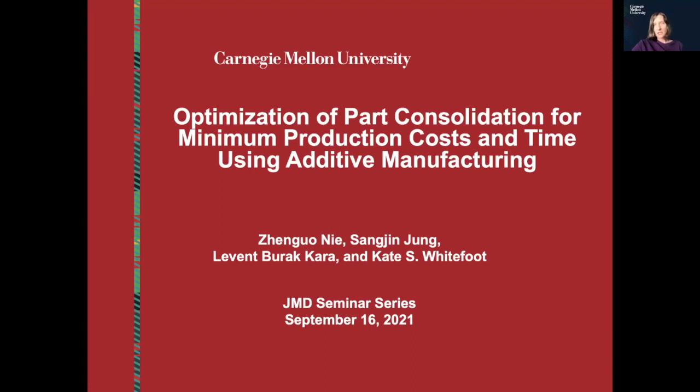And so in those cases, the key there is really the time that it takes to conduct the assembly operations, and then costs associated with labor and inputs. For our systems, we see that riveting is a more expensive assembly operation than welding in this particular case. And so with more expensive assembly operations, that gives you an incentive to consolidate further parts together, because that is a larger driver relative to the support structures.